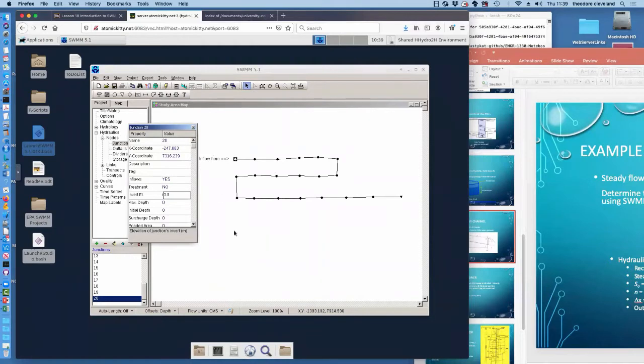So the second most nuisance thing about SWMM that I think you'll find is it never uses slope as an input. So we actually provide elevations and it will compute slope, which from an engineering design and operational standpoint actually makes sense. But apparently the hydraulic authors 40 or 50 years ago never got the memo from the future. So everything in our textbooks is based on slopes.